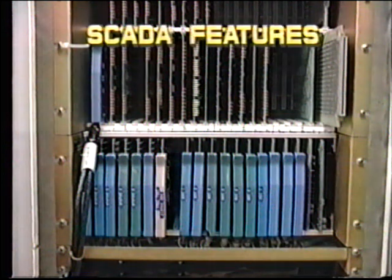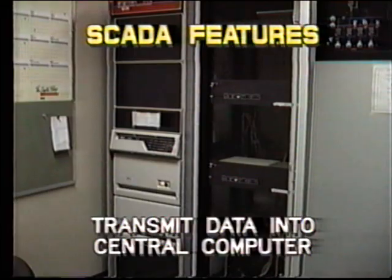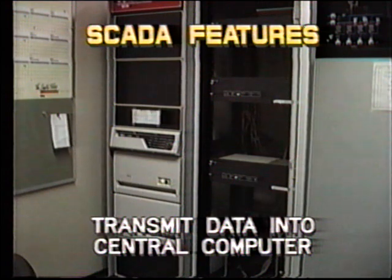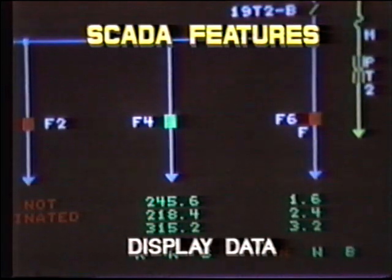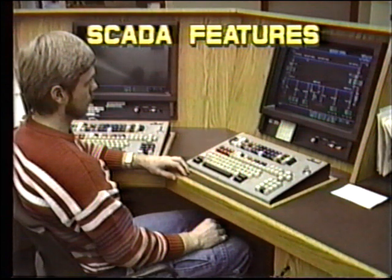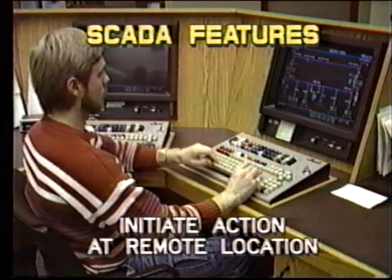The essential features of all SCADA systems are the continuous collection of information related to current operating conditions from many locations throughout the system, transmission of this data into a central computer, which is programmed to evaluate and make appropriate decisions, display of this data to allow operator interface, and transmission of control command signals from the computer to a remote station in order to initiate action based on operator or computer decisions.